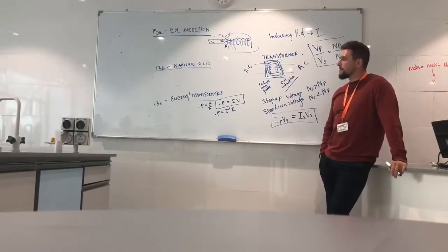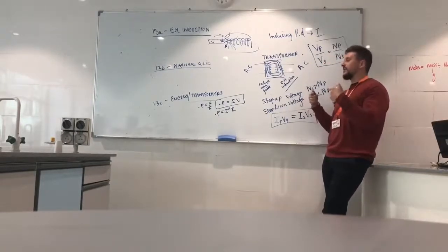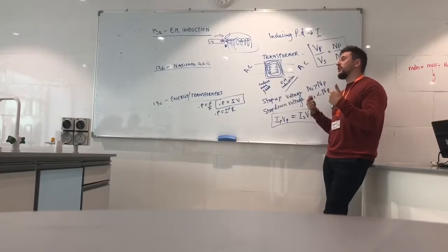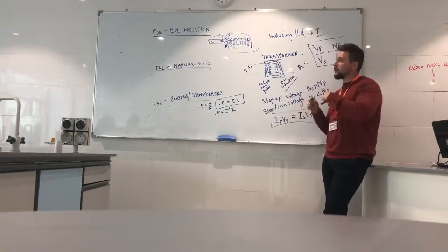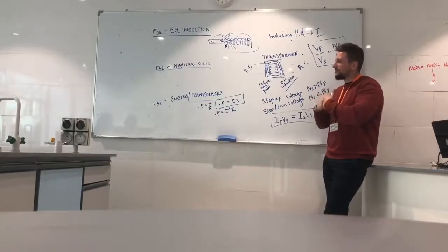What's a carbon brush? It's just a conducting material that connects to the coil on a motor or a generator. We don't use metal because it grinds away. So we use a conducting material that can touch the coil, the slip rings or the commutator, and allow it to turn and touch without grinding away.